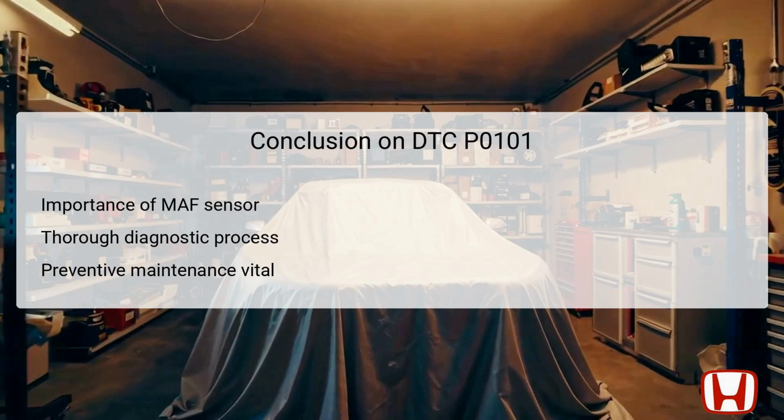In conclusion, DTC P0101 highlights the significance of a properly functioning MAF sensor within the engine management system. A thorough diagnostic process is essential in identifying the source of the problem, ensuring that no potential issues are overlooked, from poor connections to physical damage in vital components.